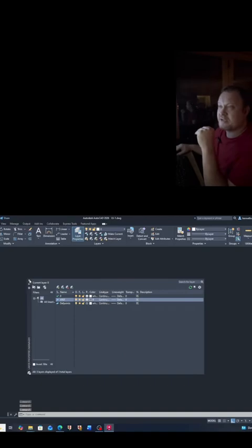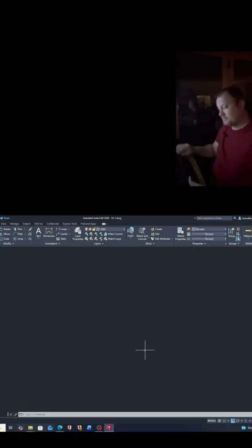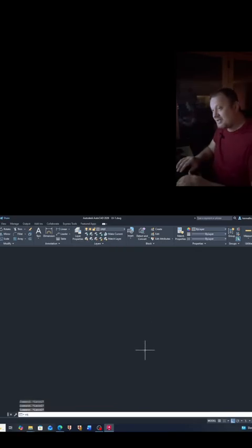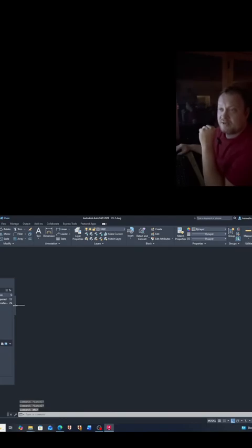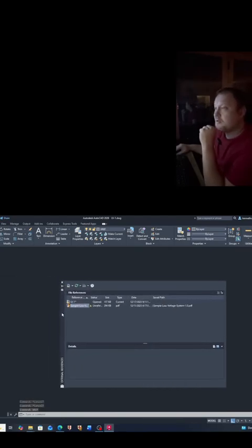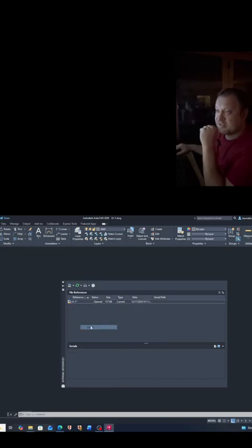We got our layer called XREF. So let's go up here and select XREF. And now just type in XREF. And I'll expand this window here. So it's showing this because we had imported that PDF before, but we've deleted it. So let's just hit detach.